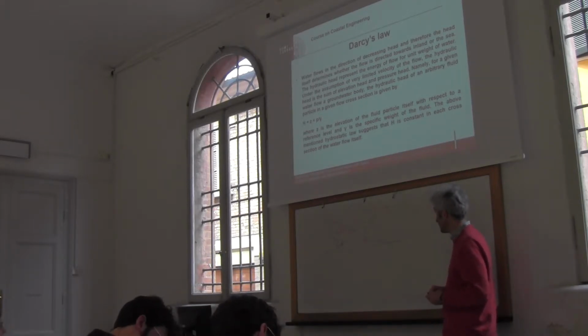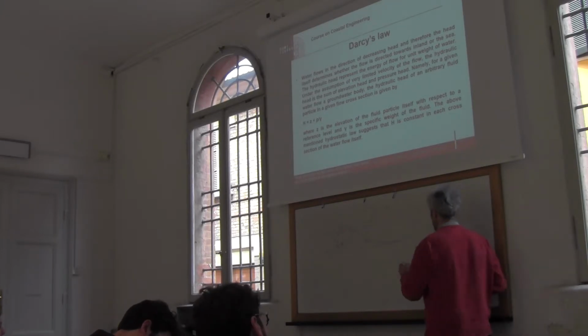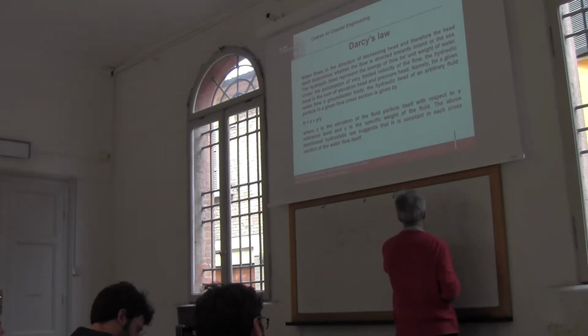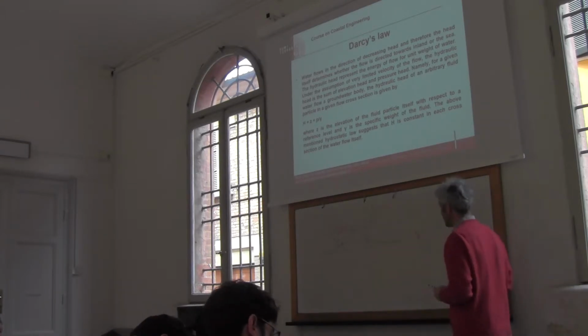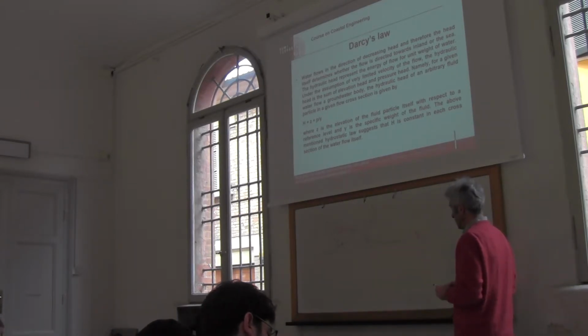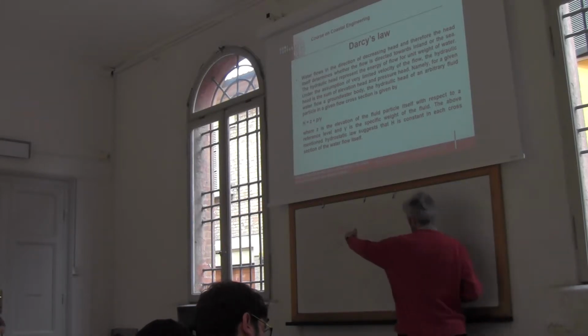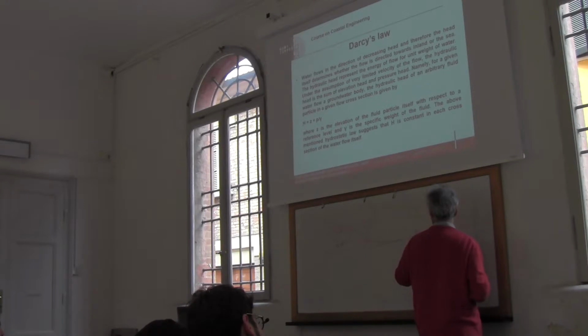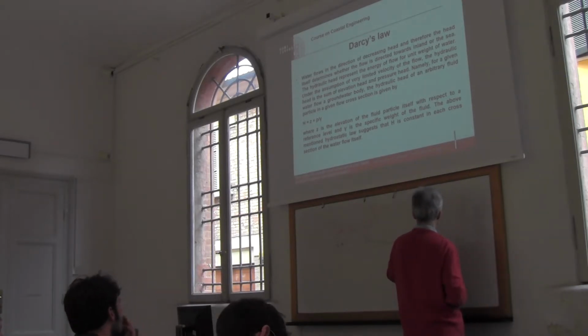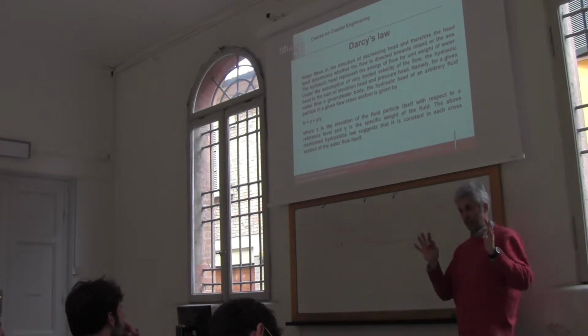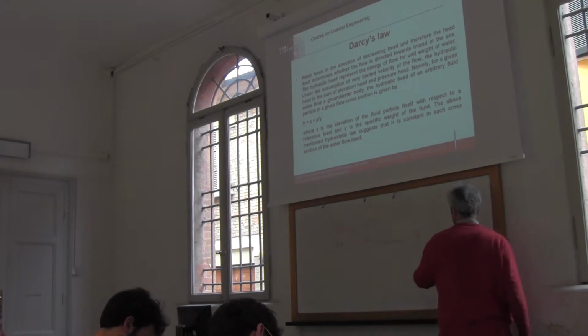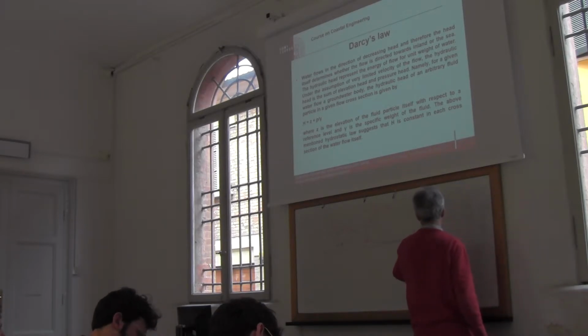Okay, and in this case I can write that this is Ps. Let me write that Pf, where f stands for fresh water, is given by the total height of the water column here, which means gamma F, because now I have to consider the weight of the fresh water, times H plus hf.